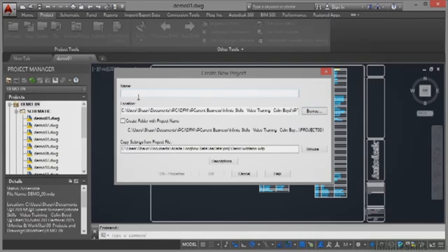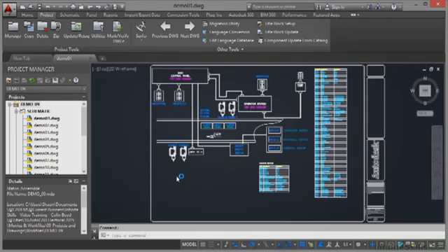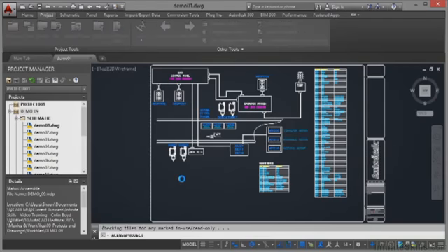I'll give the project a name, Project 001. And do I want to create a folder with that project name? No, I don't, because the folder's already there. However, I could just point to a location and create a new folder like so. What it's going to do as well is copy the settings from the WD demo WDP file. So if I now go OK Properties, like so, it'll allow me to set up my project properties.